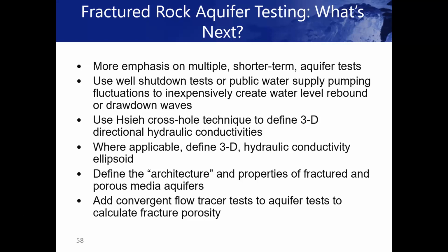Okay. All right. Short-term tests are great because they reduce costs, but longer-term tests can identify boundary conditions that may be important to understanding the overall aquifer conditions. Is this an issue in relying only on short-term tests that characterize aquifers close to where the stress is applied?